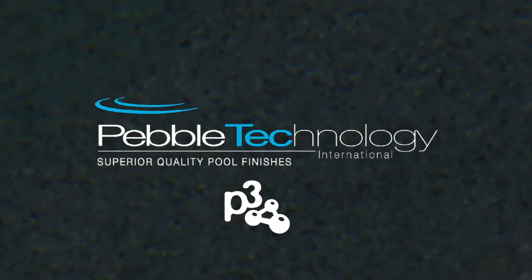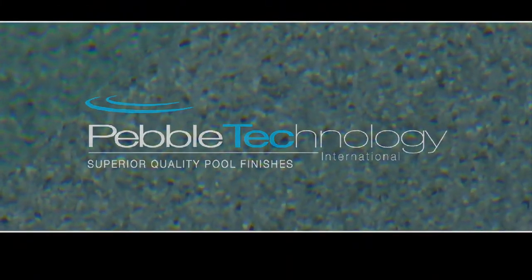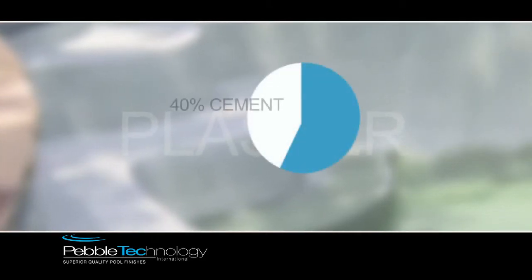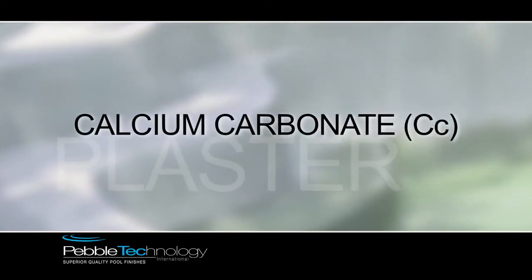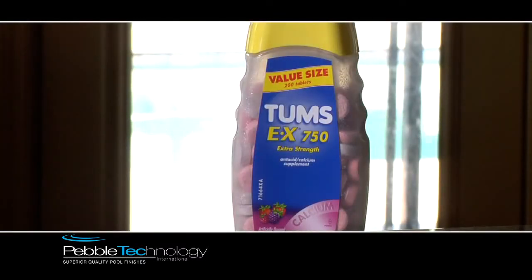Before we get into the virtues of Pebble Tech, let's take a moment to understand the properties of plaster, which is a generic term. Plaster used to consist of pure silica, cement, and asbestos. It is currently a mix of 40% white Portland cement and 60% crushed marble. Its chemical term is calcium carbonate. An interesting side note is that the main ingredient in the product in front of you, Tums, is calcium carbonate.